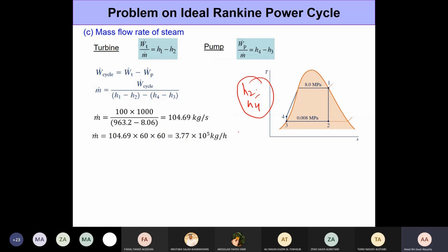Now, we calculated the thermal efficiency of this plant to be 37.1%, but just relying on energy efficiency is not enough. We need to compare it with the situation for a reversible cycle, because just looking at 37.1, it looks like a low efficiency, right?